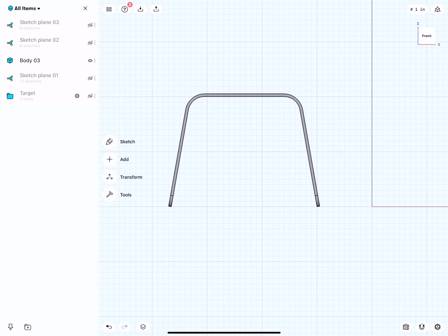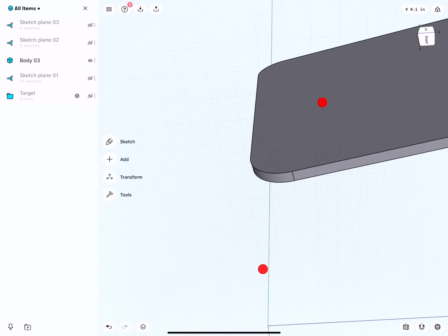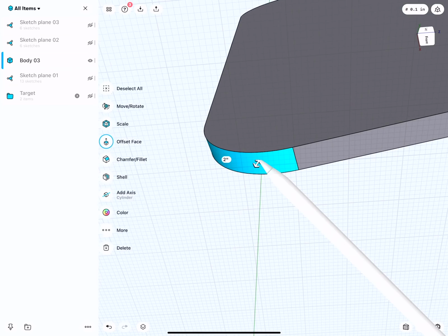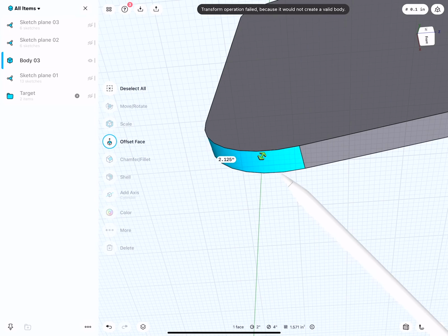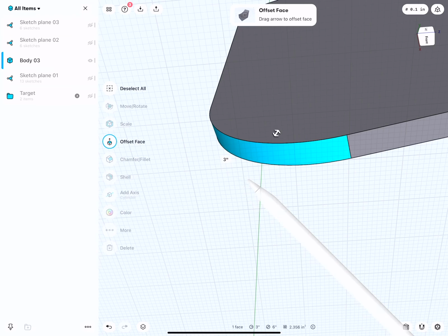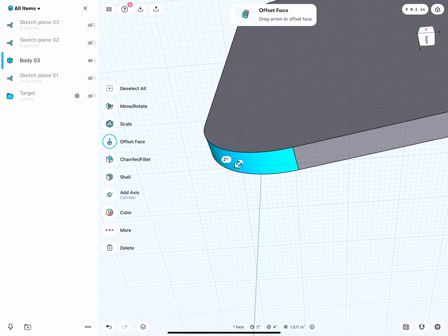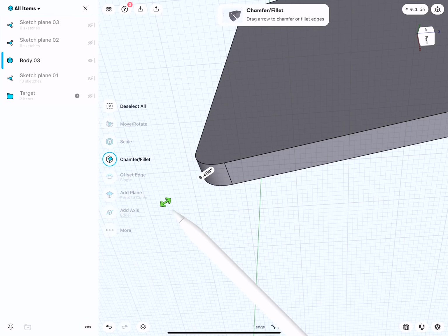Maybe we would like to adjust the position of the handle. Maybe we would like to adjust the radius of the roundings here. We can select this rounding afterwards and still override it. So it's pretty cool. This can be adjusted whenever you want, which is really nice. I can also select this fillet and then click on delete, and I actually get my original edge back. Pretty cool.